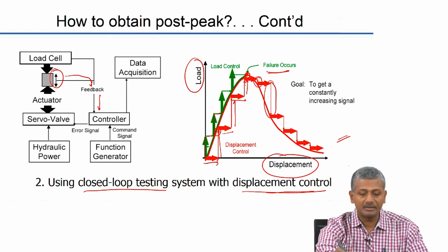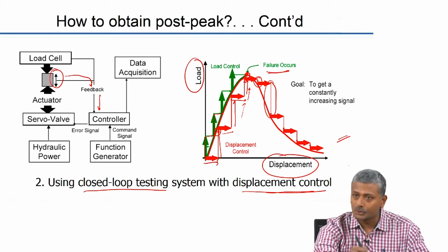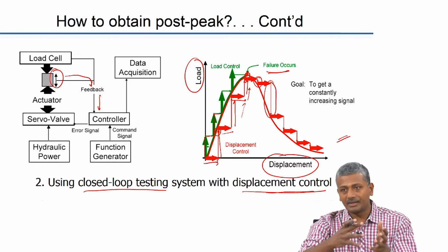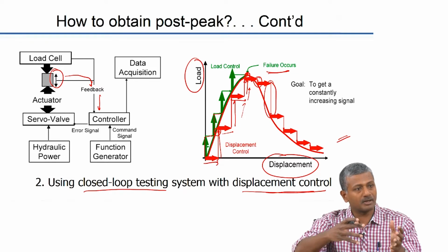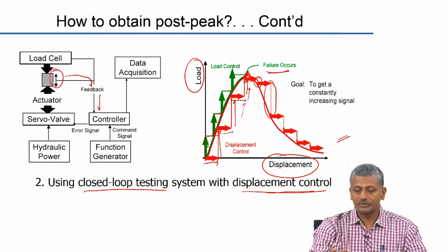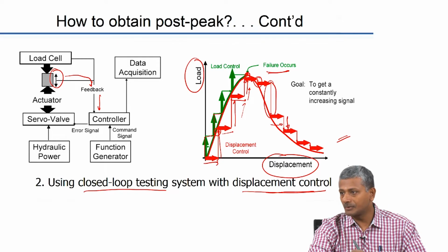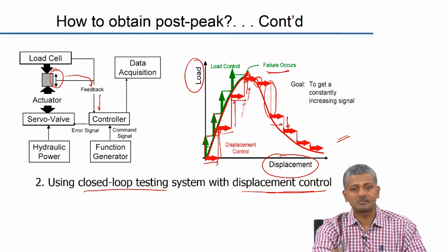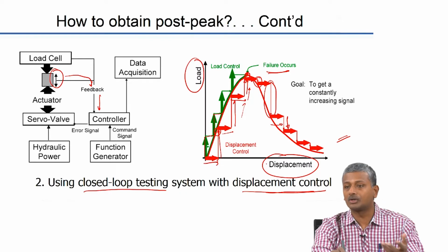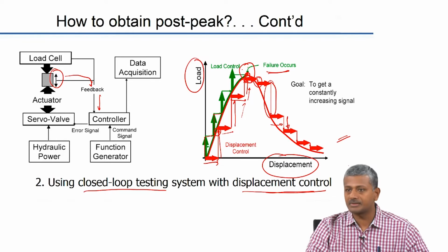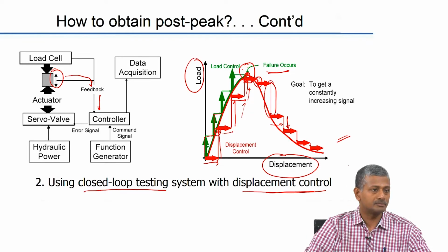Okay. Earlier you needed lesser increments of load, but now you actually need reduced load to actually reach the same level of displacement, because the cracks have already localized and all you have to do is now open up the cracks to lead the material towards failure. So, as you keep on giving the same incremental displacement, your actual load registered in the machine will be lower. Okay. And this can only happen in the case of a displacement controlled machine, because if you are doing a load control beyond this point, you are not going to be able to increase the load further, because any increase in the load will completely collapse your material.